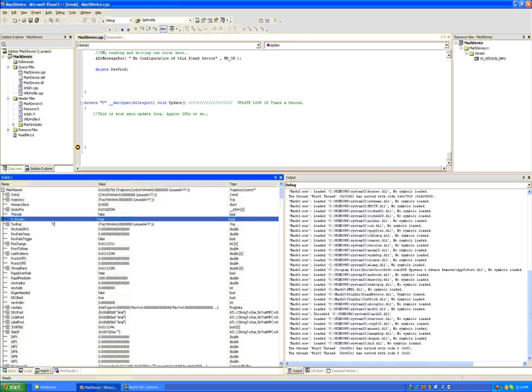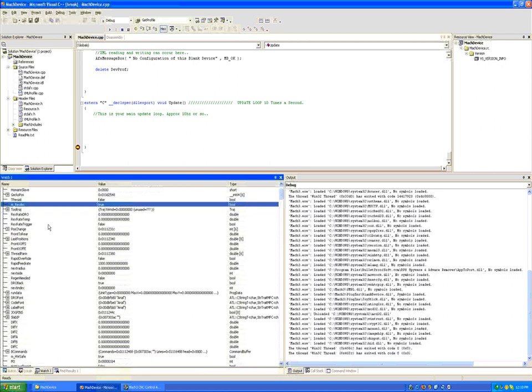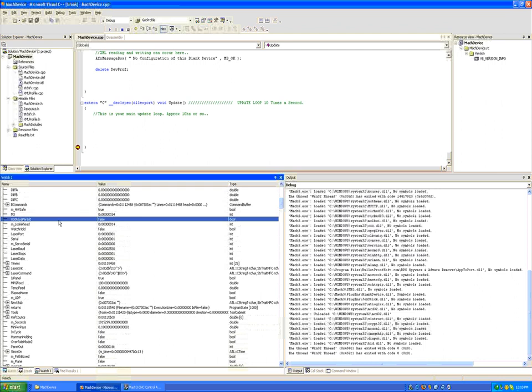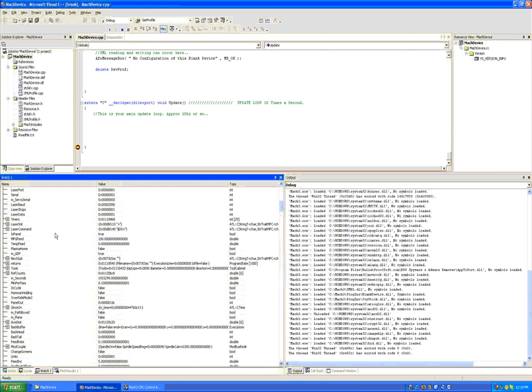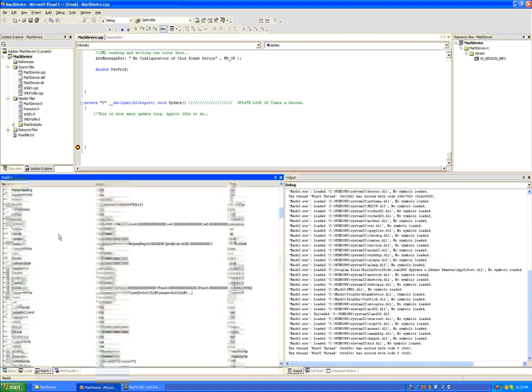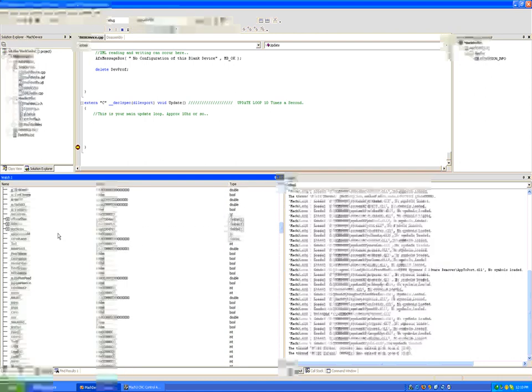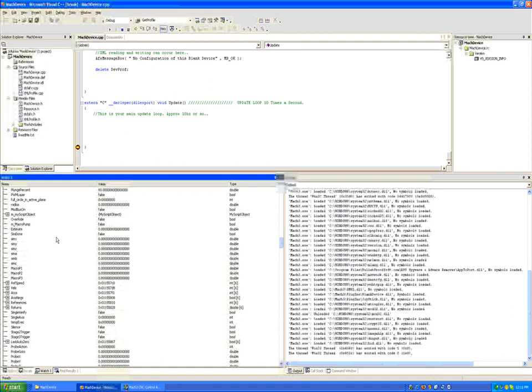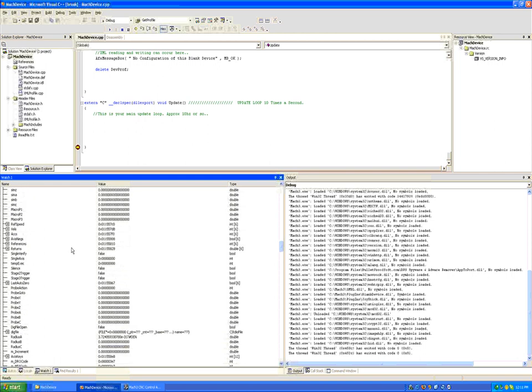M_reverse arc. This would cause arcs to reverse their direction from a G2 to a G3. Again, you're going to want to look through, do hotkeys persist? They're set to false at the moment. Laser stops, laser baud rate if you were speaking serial to a laser. There are several hundred variables here, all of which are attachable. You may want to set up Mach3 so it's set in a particular state, set a variable to a magic number that you could search for here and say, there's my variable, this is the number it is set to, and then you're free to play some games with it.